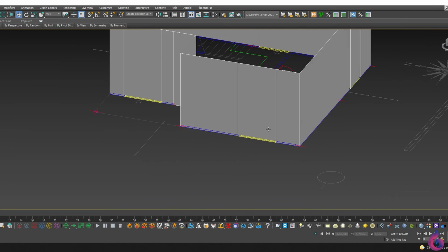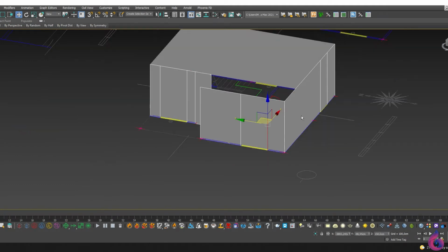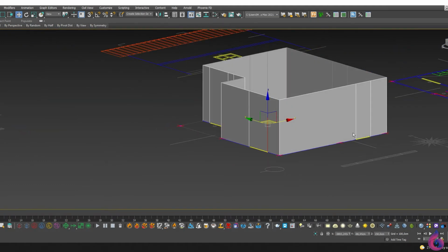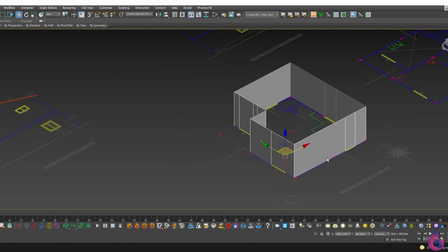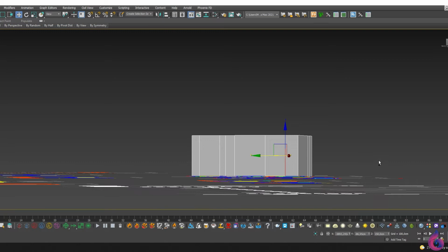Here we are, and what you see is our window. We want it to be about 80 centimeters from the ground. Instead of selecting each edge individually, we have several options. The first is to change the perspective. Hold Ctrl+R and select every edge. The second is to select one of the edges, press ring and then connect.